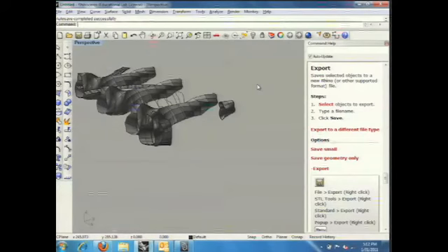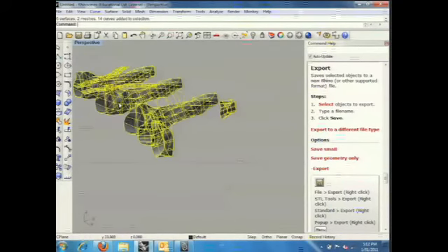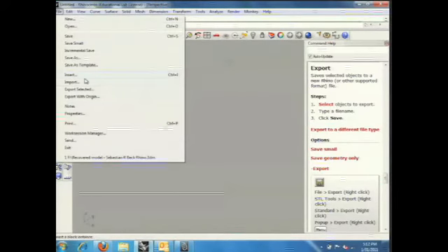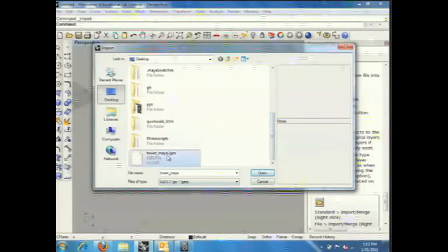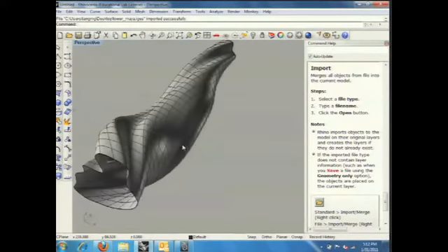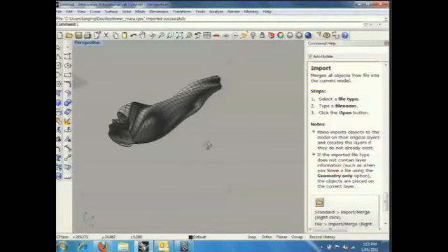Know how you can do it with some simple tools. First, let me just get rid of this stuff. I will just import geometry directly from Maya, which I did last class, right, with IGES. Remember that? This is a file format. You can create a connection between Maya and Rhino. So the form came in rotated 90 degrees because Maya is Y up, Rhino is